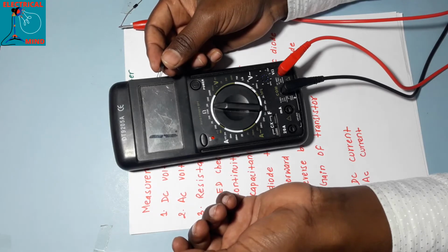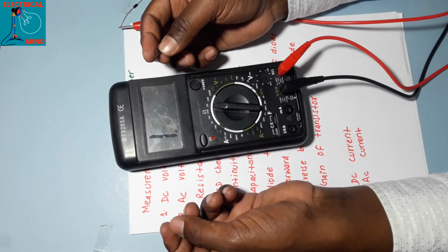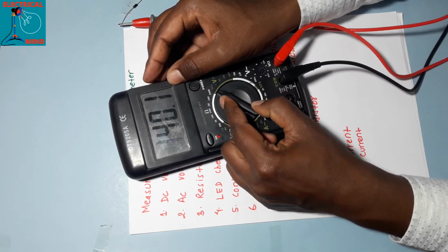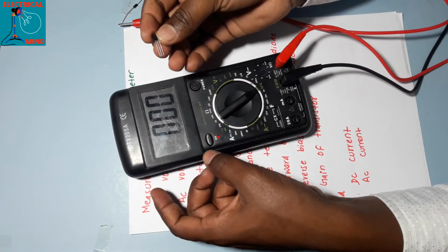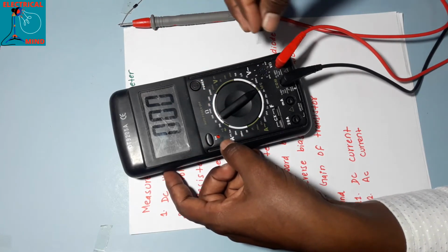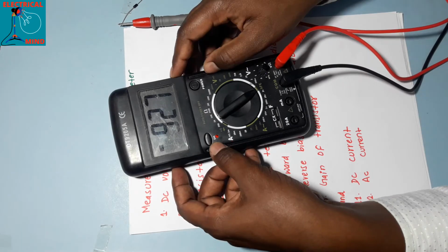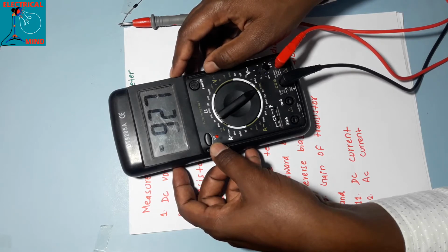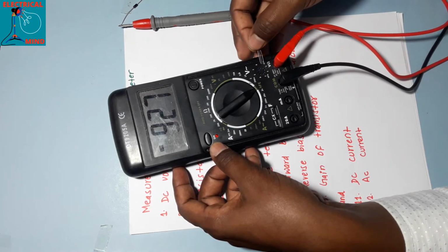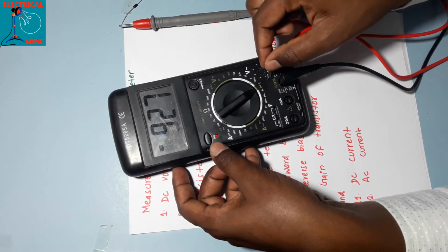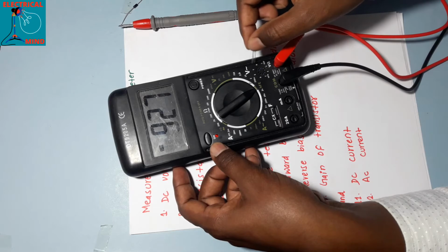Point number 10, gain of a transistor. As we already know, a transistor has 3 pins: emitter, collector and base. To find the gain of a transistor, set the pointer to HFE. This is a PNP transistor. To measure the gain of a PNP transistor, I am setting these 3 pins in these 3 holes. As you can see, the multimeter is showing the gain of this transistor as 927. This is how you can measure the gain of an NPN or PNP transistor. If you have a PNP transistor, set this pin in the right side. If you have an NPN transistor, then set this pin to the left side as written on the multimeter.